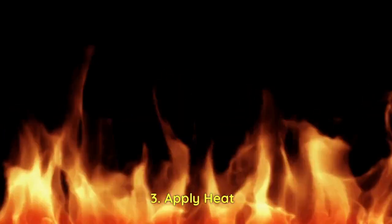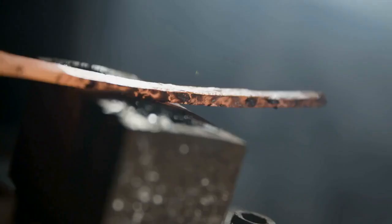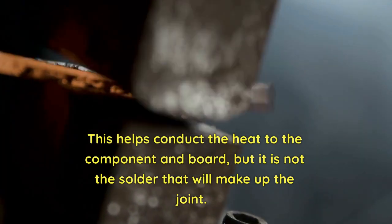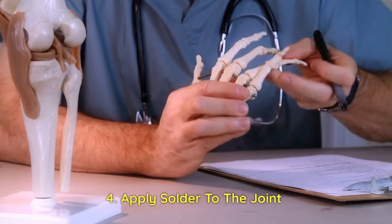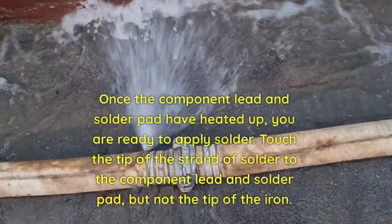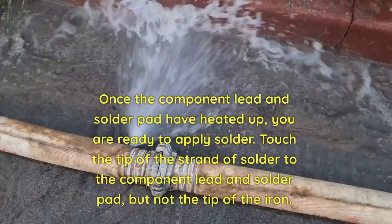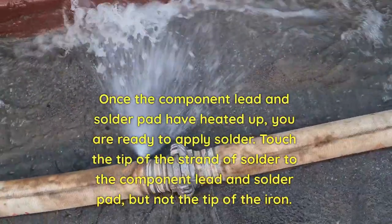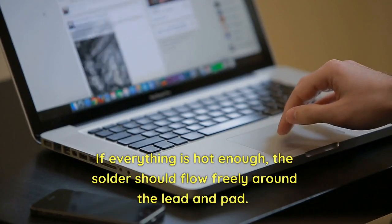3. Apply heat. Apply a very small amount of solder to the tip of the iron. This helps conduct the heat to the component and board, but it is not the solder that will make up the joint. 4. Apply solder to the joint. Once the component lead and solder pad have heated up, you are ready to apply solder. Touch the tip of the strand of solder to the component lead and solder pad, but not the tip of the iron. If everything is hot enough, the solder should flow freely around the lead and pad.